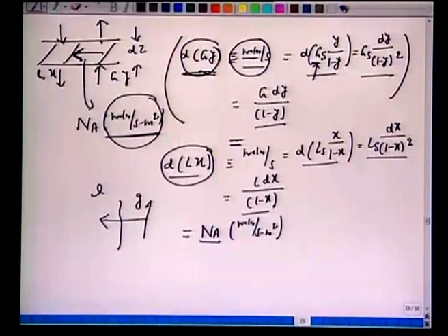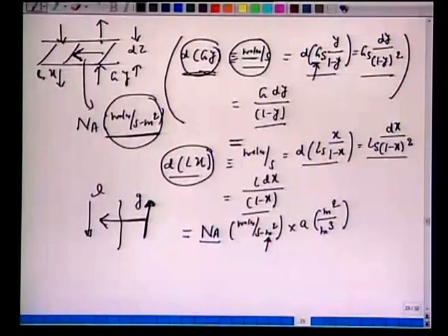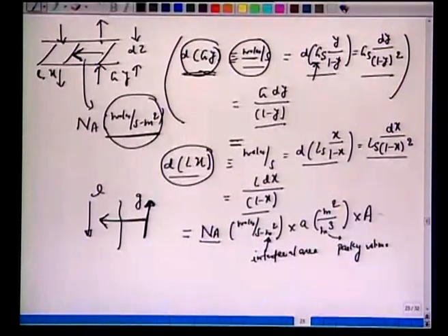So, whatever changes here, there is a decrease and there is an increase, which is balanced by this gas to liquid transfer, and will equal NA into A, that is the packing specification, meter square per cubic meter. Make a note, this meter square is not the cross sectional area, this is the interfacial area of mass transfer, and we have this packing volume. So, this multiplied by the cross sectional area of the column, At, into dz, that will be our moles per second.